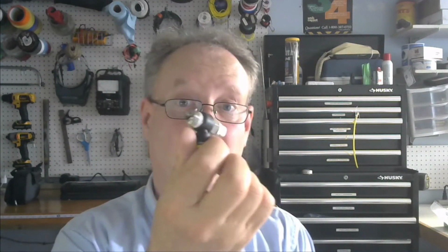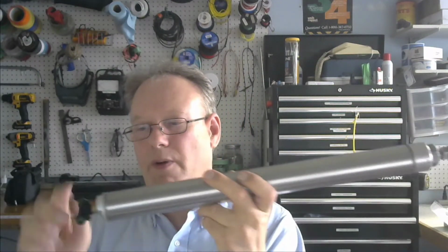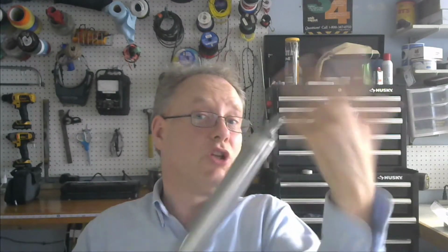Well, I use a non-return throttle valve. And the thing about pneumatics is, generally, we meter out in pneumatics. We don't meter in pneumatics. And I'll try and explain that. If I were to put pressurized air in here and there was no load, generally when there's no load or very little load, we always meter out.